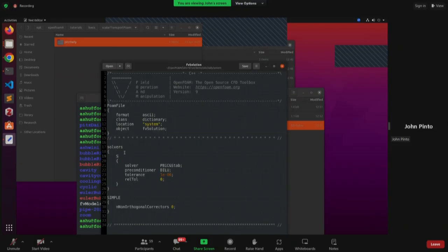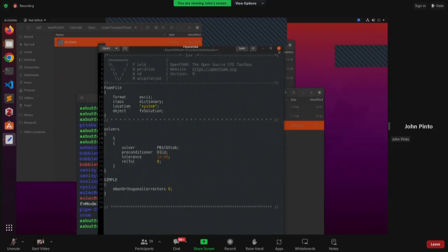We are only solving for the scalar, right? And velocity is our initial condition, and that velocity does not change. That's why we don't need to solve for velocity. So velocity is imported from a previous simulation, and that is used as an initial condition for this simulation. So these are the changes that you need to do. Okay. After you do this, I think you are done.